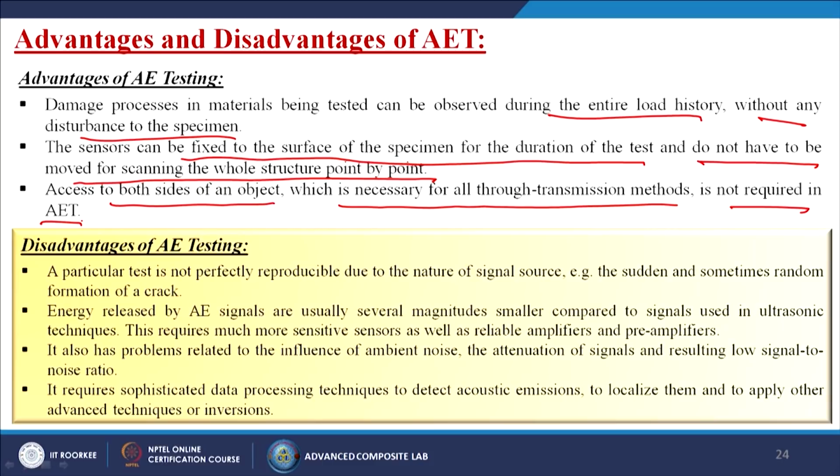Of course, we have certain disadvantages also. What are those? A particular test is not perfectly reproducible due to the nature of the signal source, the sudden and sometimes random formation of cracks, because we do not know what will happen inside the material. So, pre-planned testing is not possible.